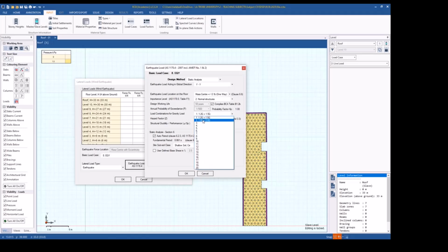Load combination: here I trust you're going to ask me, you would need to change it to the combination you had. So define another combination. I trust it was this one, but some students may have used 0.3 for the Q. That's fine, change it. I would say it was B, was it? Yes, it was B. That's basically what you need to update. So this setup should be adequate. We're still following the static analysis.